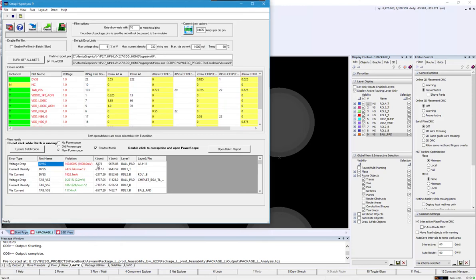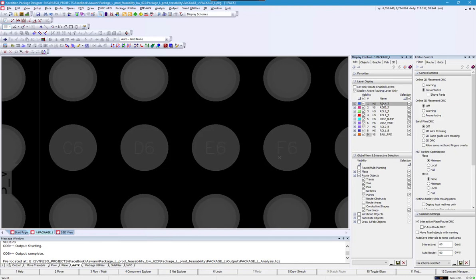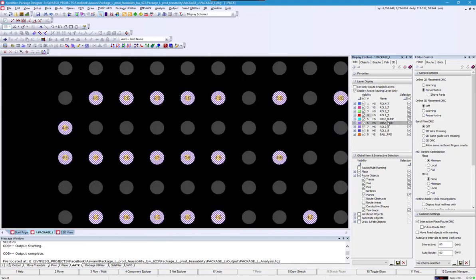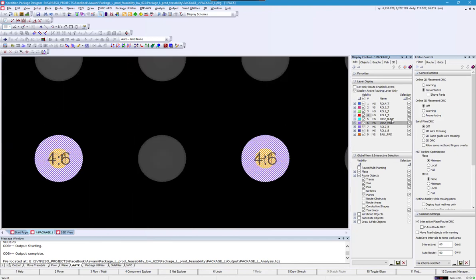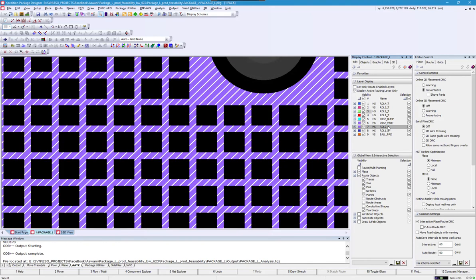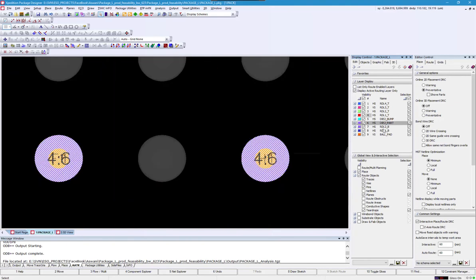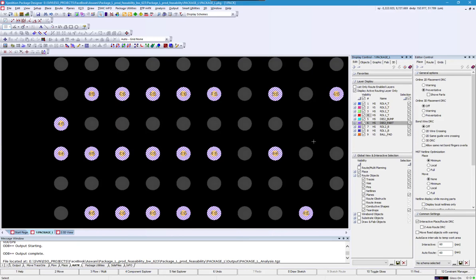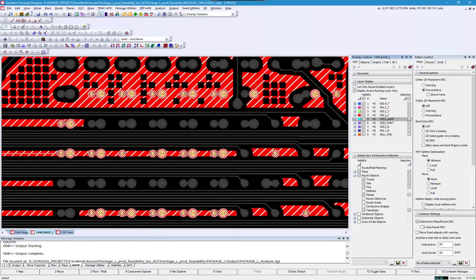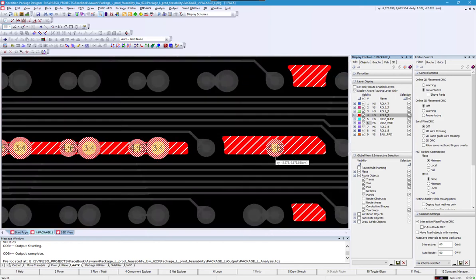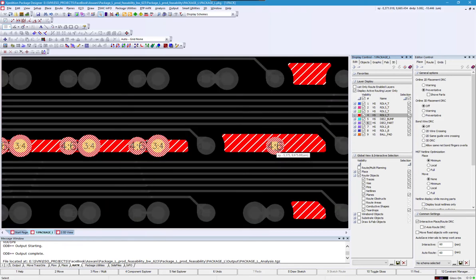What it's telling me is what layer it's on, and the ball pad on AH1 is what it's actually looking at. So what it's looking at right here is you have this internal part coming up, and we come up again. And oh, look, we have a 4 to 6 via, but this came up to a plane, and this plane doesn't go anywhere.